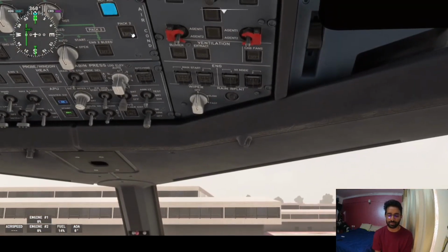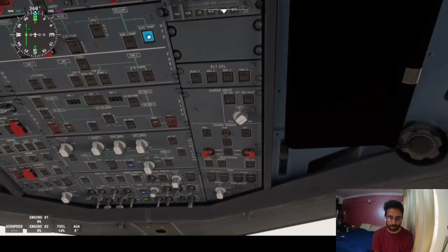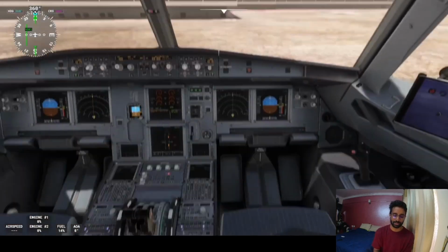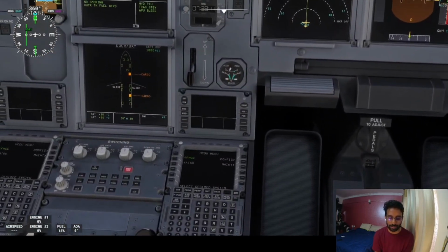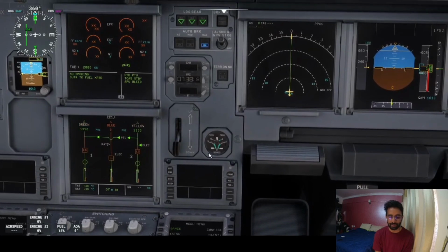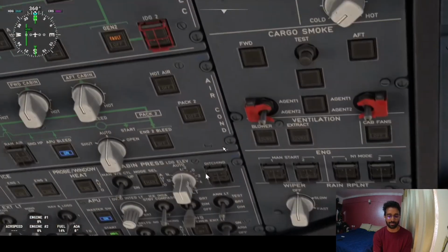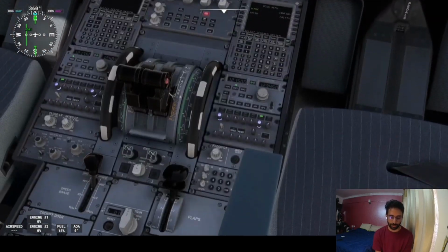So again, we will inform the ground crew. If you find in your flows that this pressure is not sufficient, tell the ground crew that you have pressurized the yellow system once your clearance is received. Same way like before, see, the accumulator gets pressurized by the yellow electric pump. And the pressure is back. Now I put the parking brake again. Now the brake pressure is back to normal. So this is the normal way in which you pressurize your yellow accumulator.